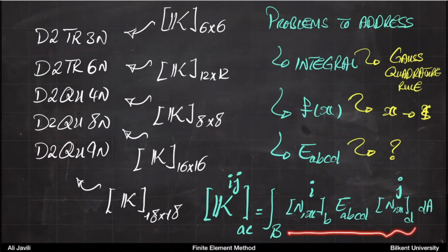Now we are back on that place where I said this is a function of X. Okay, so if you are doing it on a piece of paper, if you have a symbolic mathematical tool, you may just calculate this already. But usually that's time consuming, and what you want to do is to bring it again to the natural space so that you can also do the integration using the Gauss quadrature.